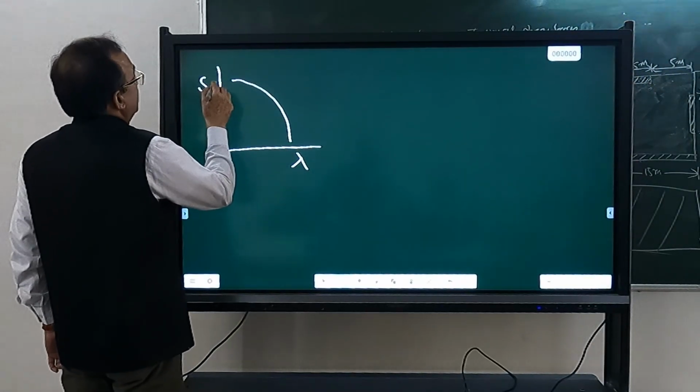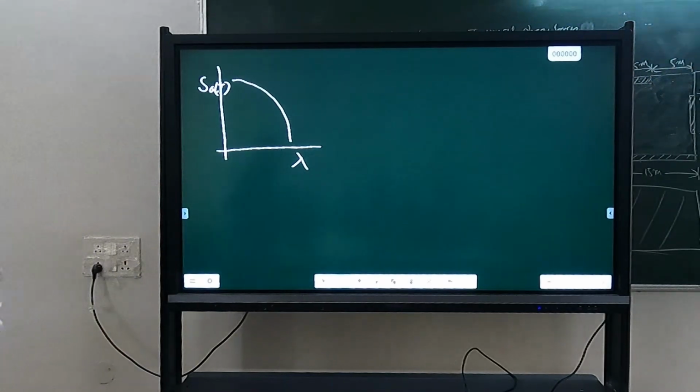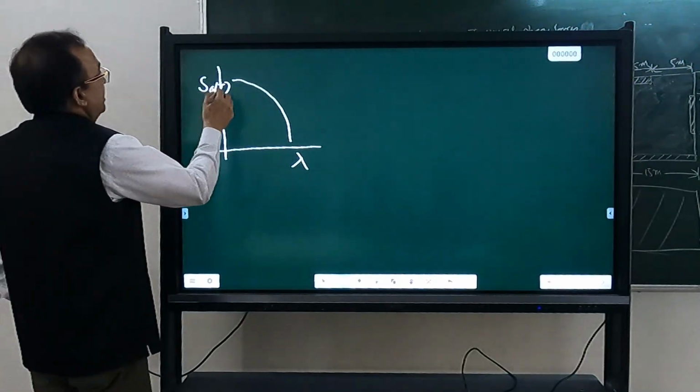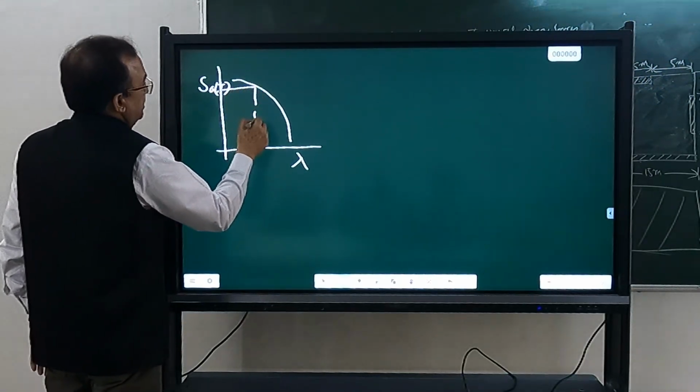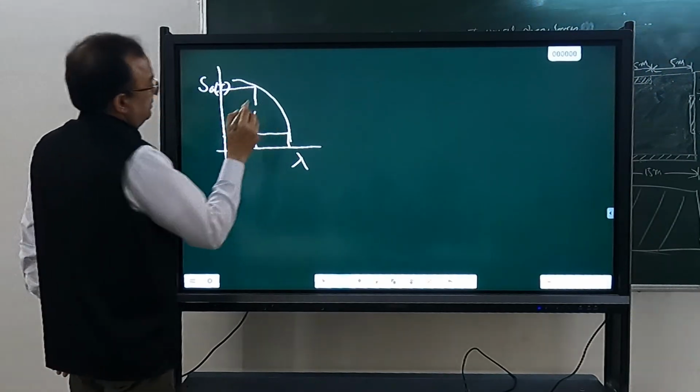Okay, so this may be at any period T. Corresponding to a given hazard, because smaller earthquakes occur frequently and larger earthquakes occur rarely, a larger SA at your structure will occur rarely, and a smaller one will occur frequently.